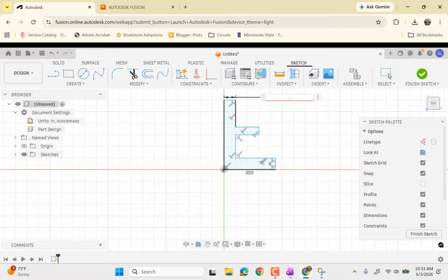That was going to be the whole thickness. The diameter of the axle is 0.1. We're only doing half of that shape though. So this is going to be 0.05. And I guess it didn't make the assumption that these would be the same. So I have to also make this one a length of 0.05.